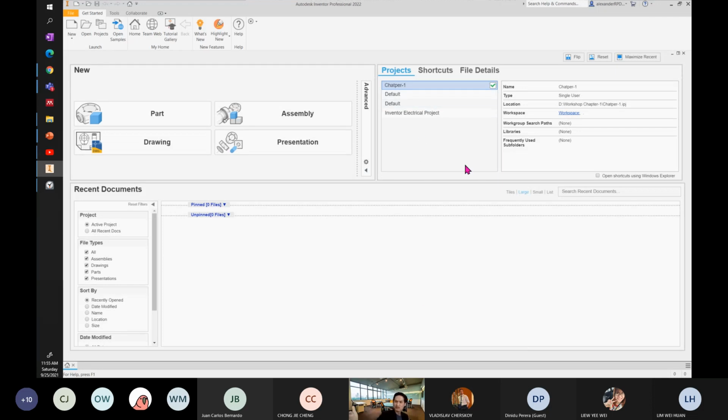So that's why if you have a lot of projects here, you can try to visualize. Project A, design robot hand, so all your design is there. And then project B, design conveyor, and all your parts are there. And then project C, design solar panel, and all your files are there. So how do you manage it? And you can even have collaboration. For example, for the robot hand, you're collaborating with Germany. Their style, their standard, the line type, the text type is different. So under that project, you can change all those, and you will not affect other project settings. So that is one of the things you must know how to manage. And you also need to know the advantage of it.